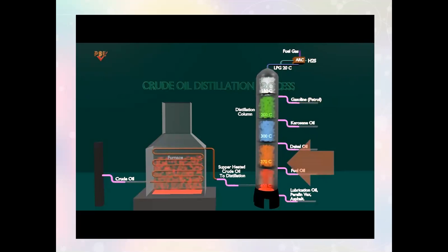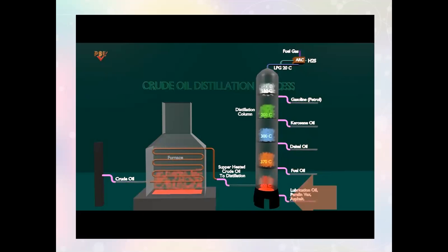Heavier distillate streams are also treated and blended into finished diesel fuel or home heating oil, or are further processed in conversion units such as fluidized catalytic cracking and hydrocracking. The routing of these streams will vary as product demand changes, to either maximize diesel production or gasoline production. The lowest end of flows: asphalt, power generation and marine